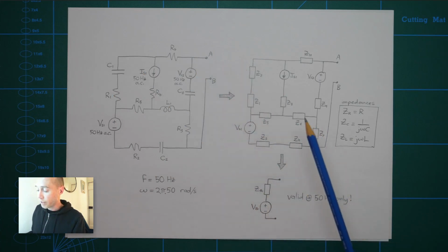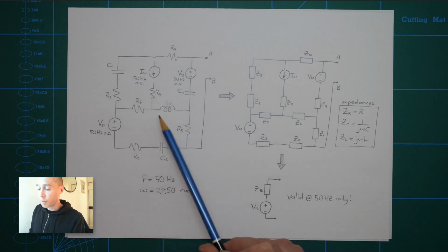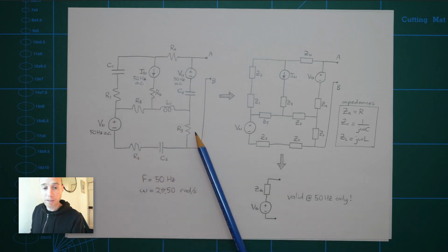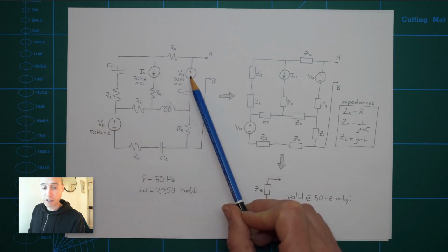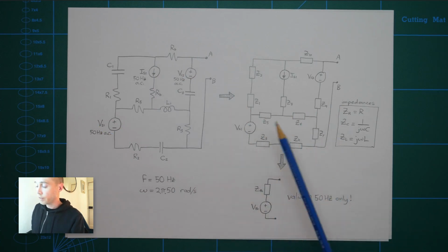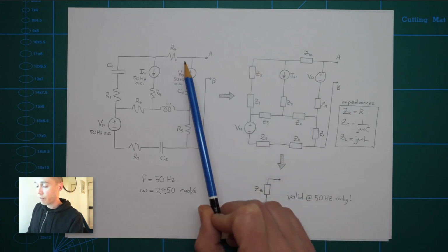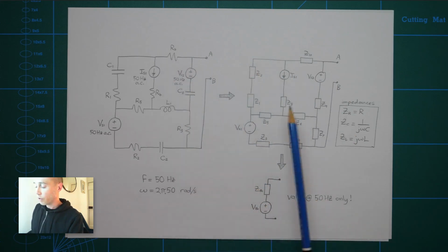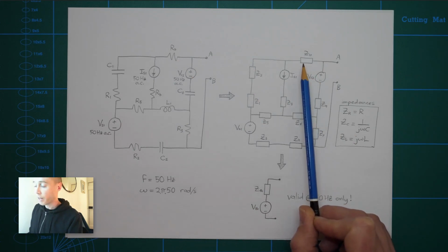We're going to be able to calculate a Thevenin equivalent circuit for this by replacing all of our passive elements with impedances, and representing these sources as phasors, and then calculating the Thevenin equivalent circuit the same way that we would have done for a DC circuit. So here I've just shown what it looks like when I replace every resistor, capacitor or inductor with an impedance, and I've just represented the impedances as these kind of rectangular blocks.